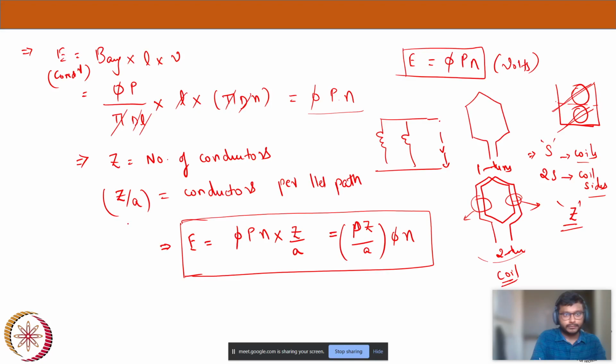Actually the windings are not like that. Let's say these are the poles, and the field winding is wound around the poles like this. Let's say this is north and this is south, and here you pass IF.